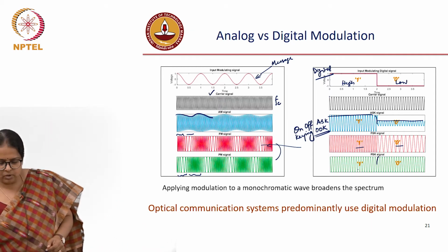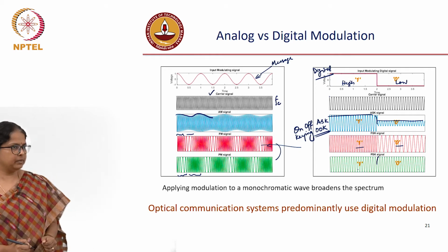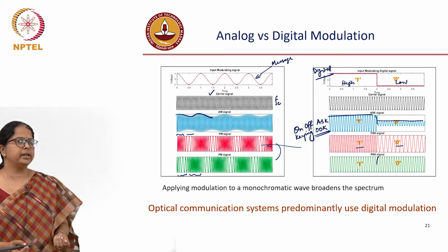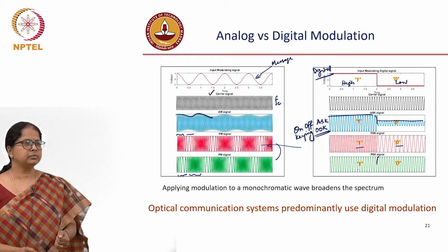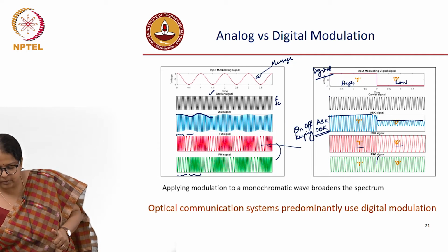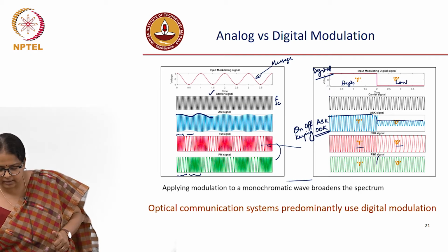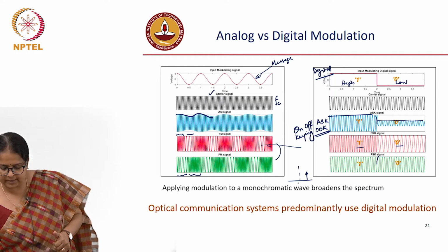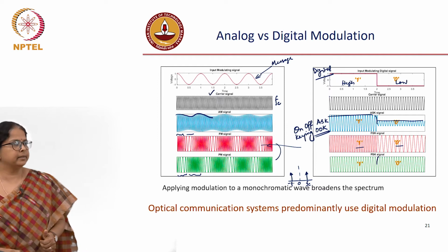Now, if you use a carrier frequency FC, what would its Fourier transform look like? If I just have a sinusoid, it will be a delta function. The frequency spectrum is a delta function, at 0 frequency DC, plus FC and minus FC for only the carrier.